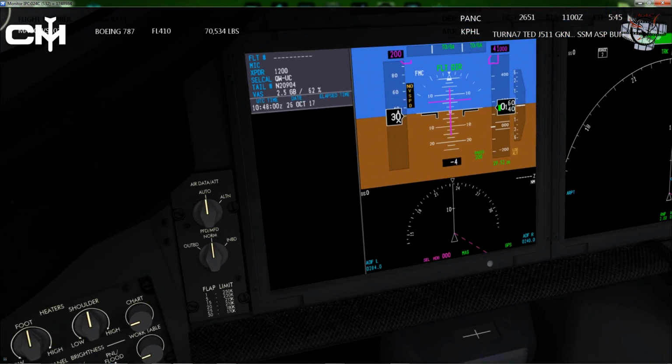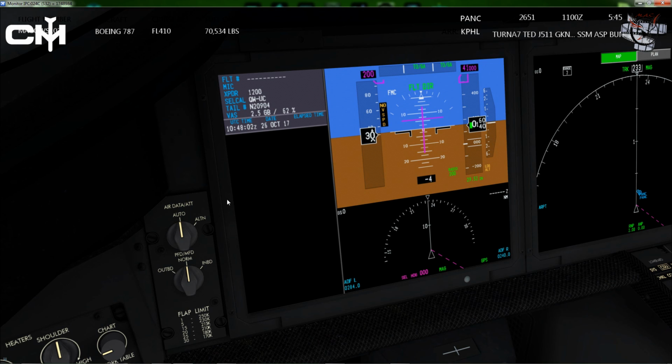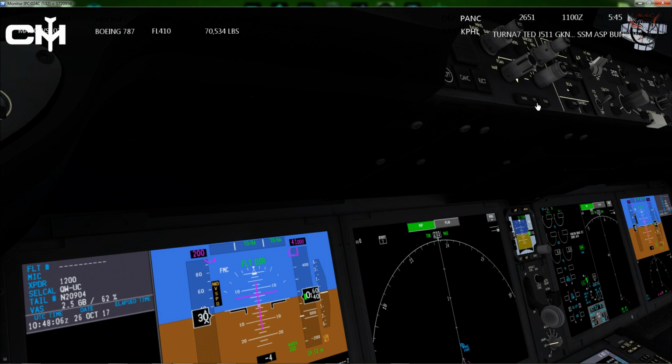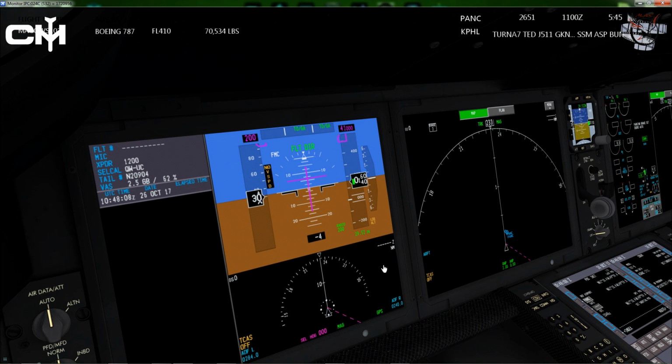And then moving over here, we're taking a look actually at our primary flight display. It should show TCAS off. It'll do that if we switch traffic here. Now it shows TCAS off. This box should be blank. This one should say TOGA. This one should say TOGA. This one should say Flight Director, and it should say no V speeds. And then of course it should show us as straight and level because that's where we're supposed to be right now. So we're looking good on all of those.